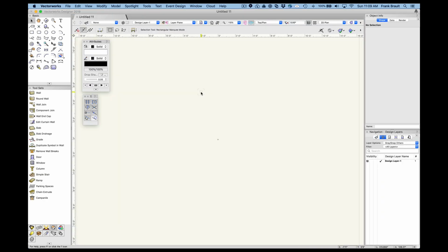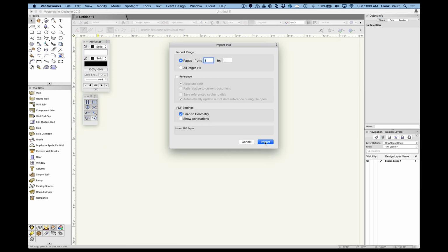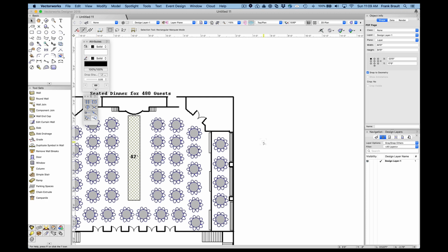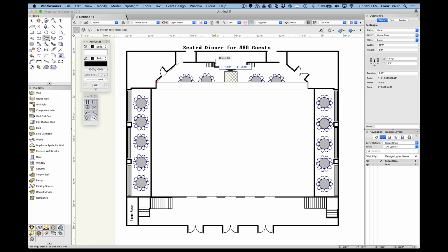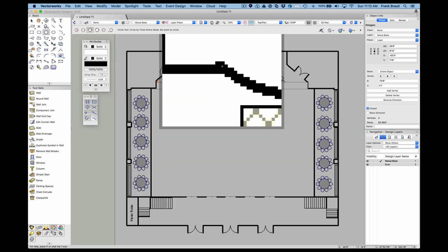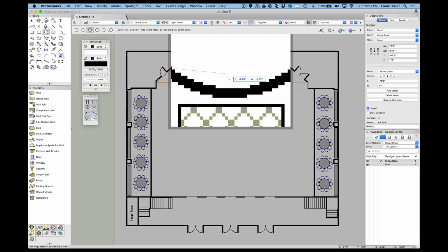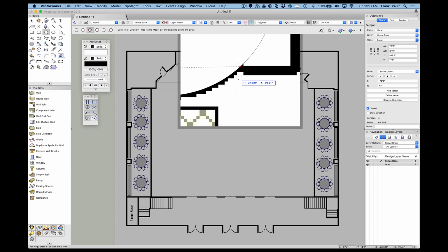Okay, moving on. For many entertainment professionals, beginning a project often involves starting with the venue. If the venue is not available as an existing file, you can start with an image file of the plan or a file with the site survey. You can then scale the image, create a new design layer for the venue, and trace some basic two-dimensional surfaces over the image, such as rectangles, polygons, and curves such as circles and arcs to represent the room area in scale. You can combine shapes and modify them in either a plan view or in a 3D view to get the shape that you need.